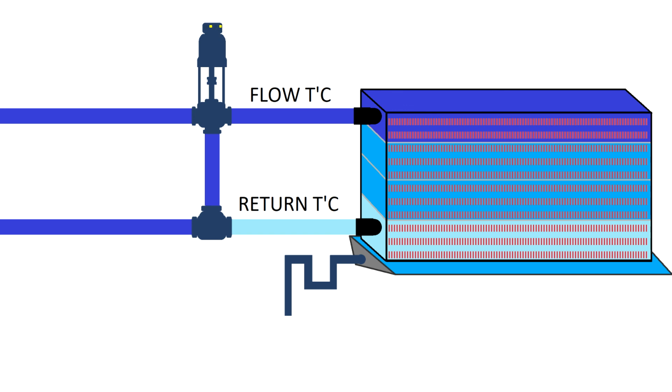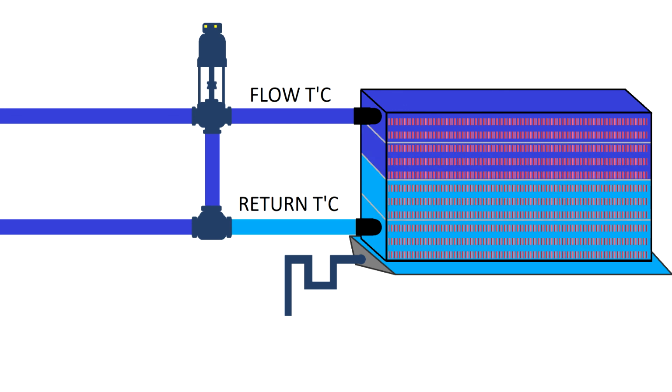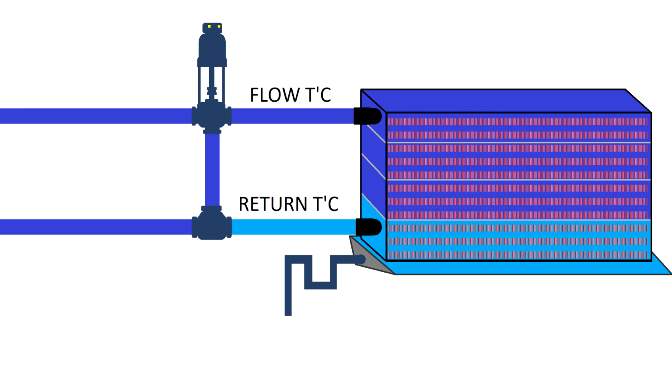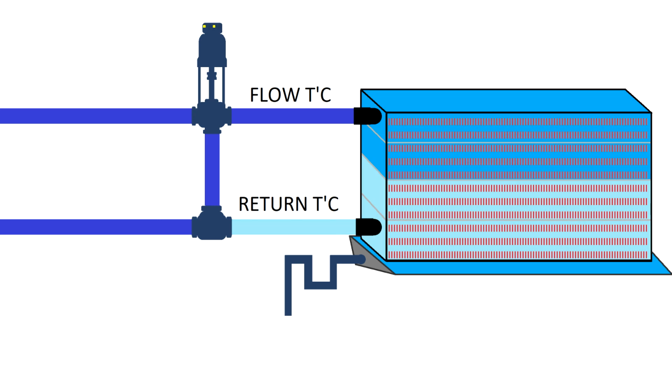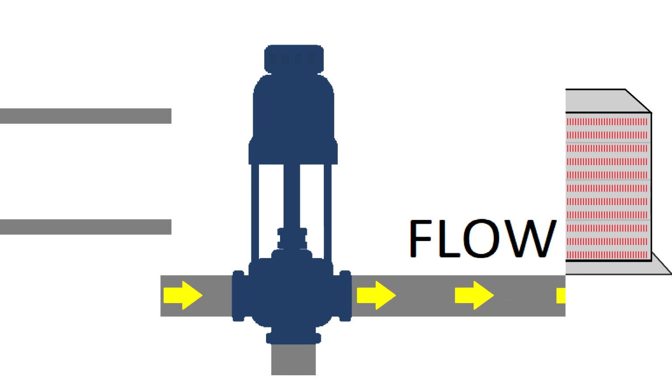Thank you very much for watching this, and let's look further at how the actuator works now. I'm going to zoom a little bit into the actuator. This is a PID system. This valve has the capability to open and close from 0 to 100% progressively. This is a great control, so you can control the heat exchanger cooling or heating capacity by opening or closing the valve progressively, and this valve controls the flow.